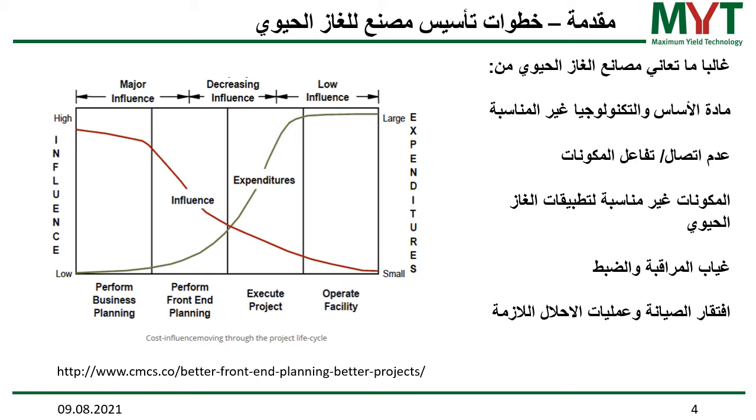Very often components from other applications are applied in biogas plants. An example are pumps, for instance. They might work for water, but they do not work for substrates in the biogas process, or mixing systems, which might work for very liquid digester mediums, but they are not working in a very viscous situation with high total solid content. So make sure that the components you're buying have been tested in biogas applications.